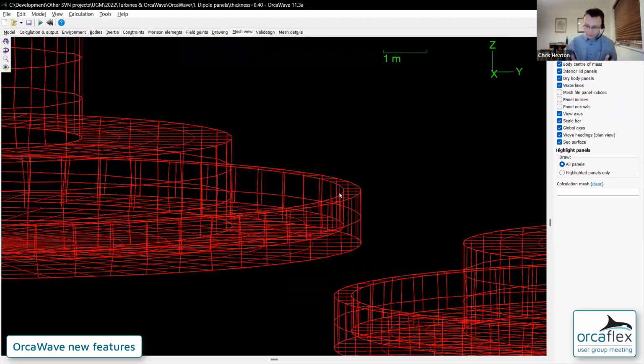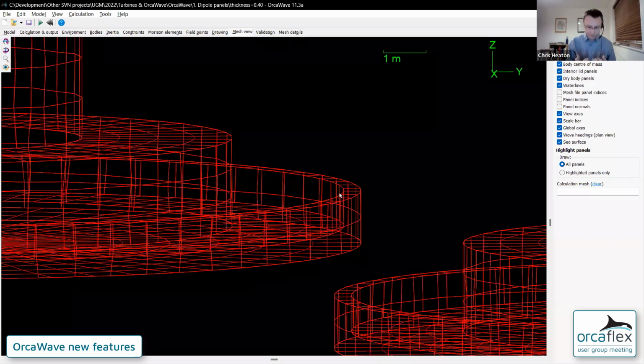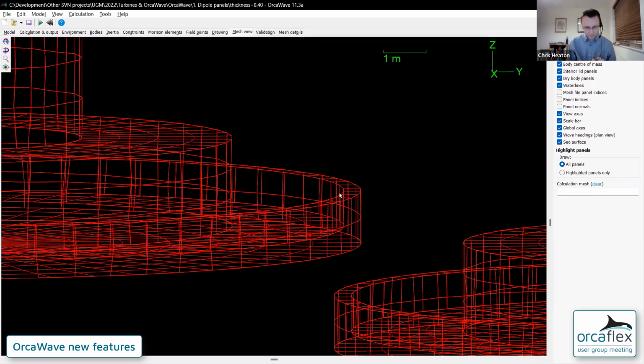So in this different approach, the shape of the platform base is obviously different. That might have an influence to some extent on the wave field. We have also changed the displaced volume and the hydrostatic stiffness and buoyancy properties as well. So there are various changes to think about, but nevertheless, it might be a valid approximation.